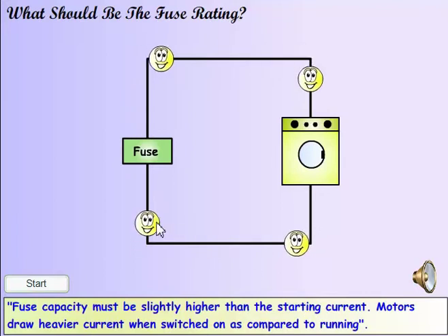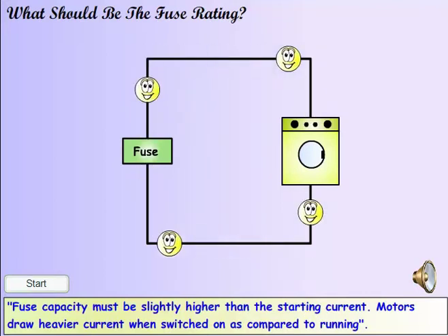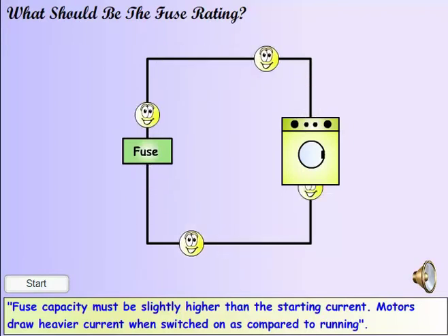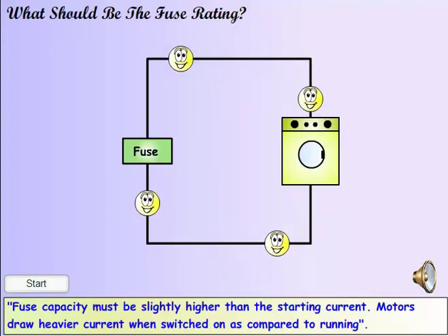When motors are switched on, they draw more current than during normal working conditions. So the current is the highest when the motor is starting. Thus, the fuse rating must be slightly higher than the starting current.